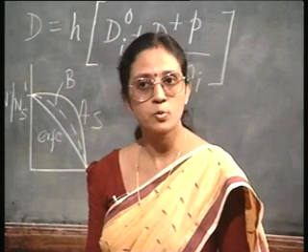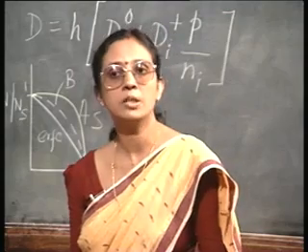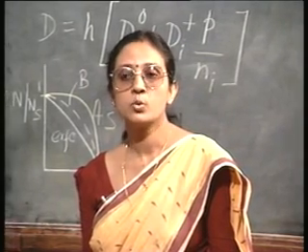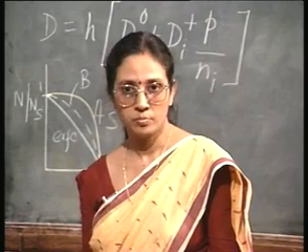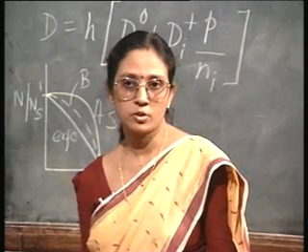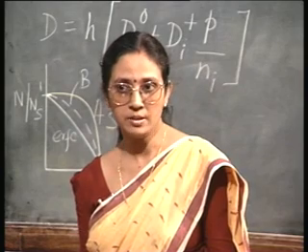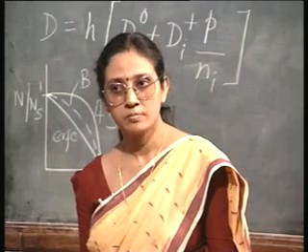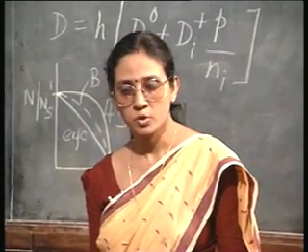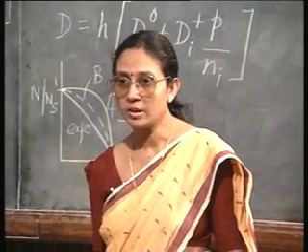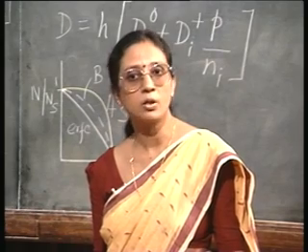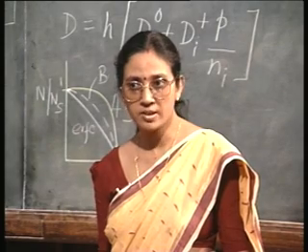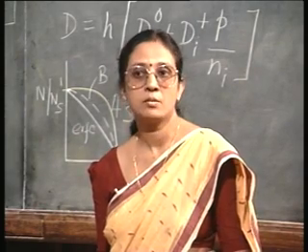Neutral vacancy trapped 2 electrons, that is how it became doubly negatively charged, right. As the Fermi level sweeps below 0.11 electron volt below the conduction band, some of the levels must be empty. So, it is not possible for these vacancies to retain all the electrons, right. The levels above the Fermi level must be unoccupied.